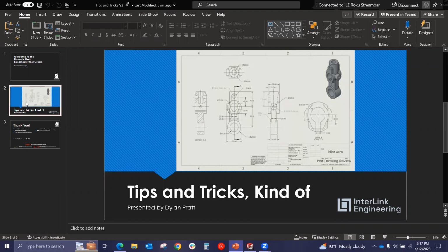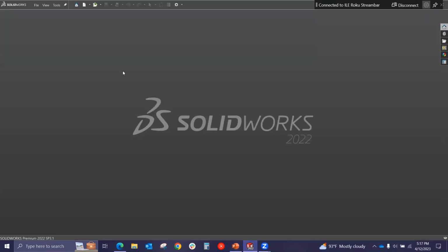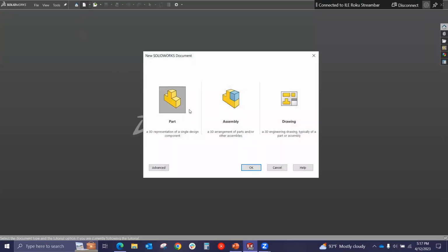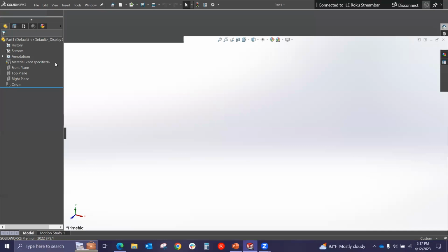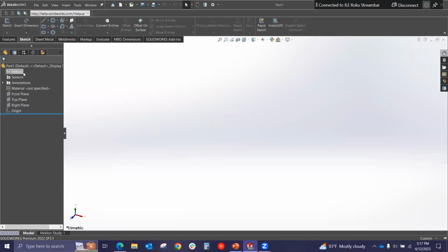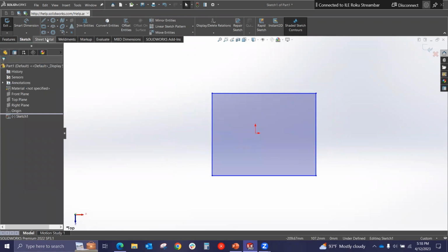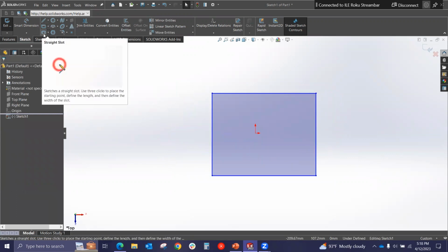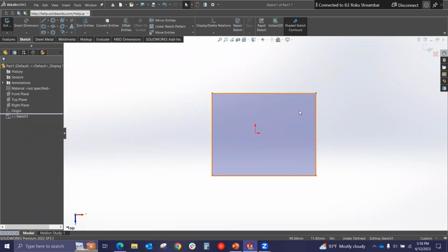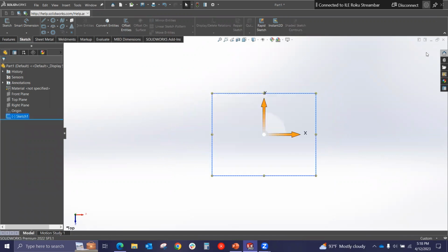Sure. When you have a transparent solid body in SolidWorks, if you want to click on it without selecting the thing behind it. It's really funny you mentioned that one, because I did that recently in a different presentation, last meeting I think. But since we're here, if you're in an assembly, you can hit Shift and select. And yes, you brought up the fact that you can actually reverse that action as well, if you'd like to.